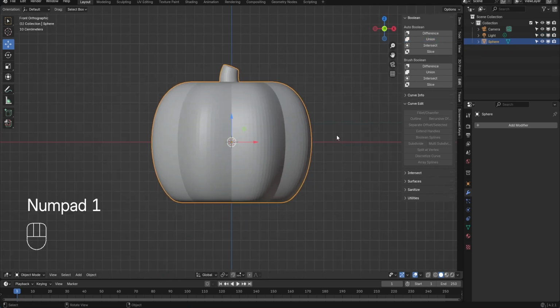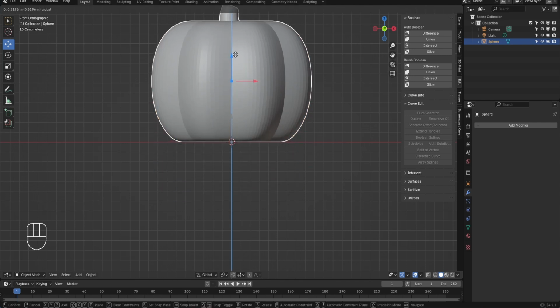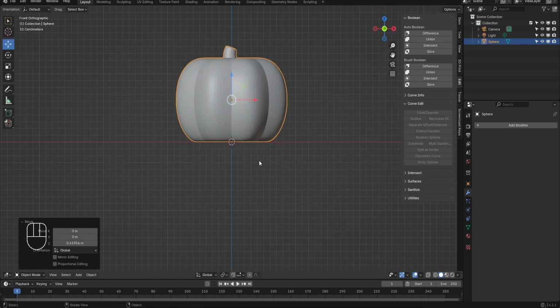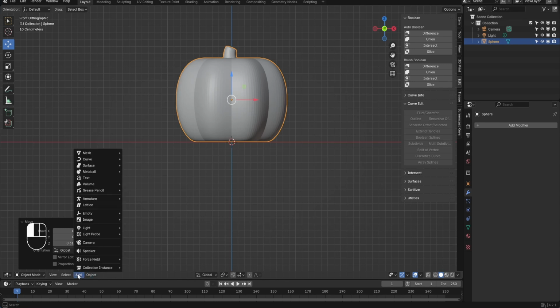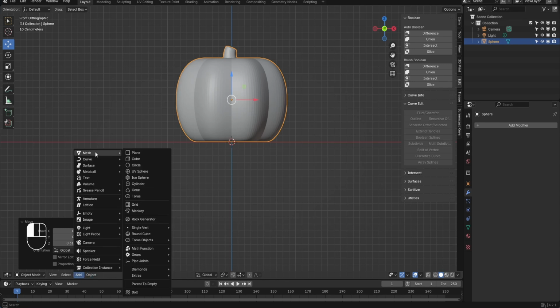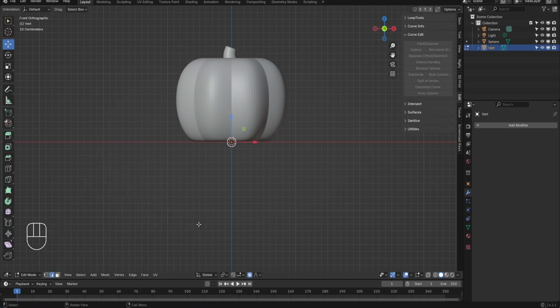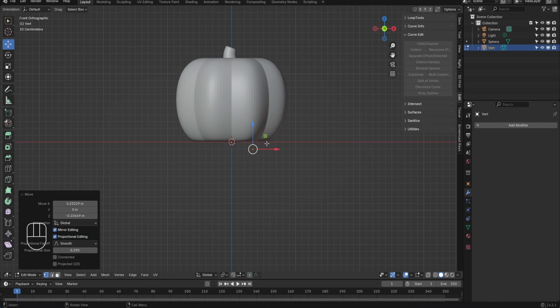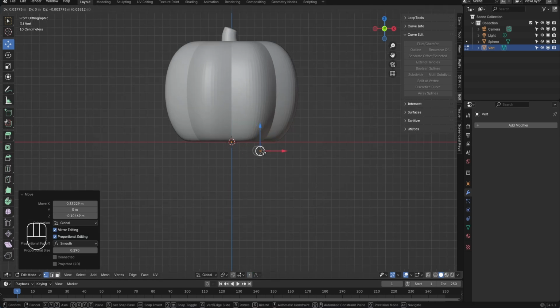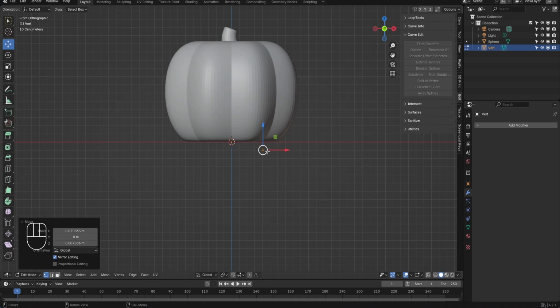Next, we are going to slice into the sphere, so let's move it up for ease of reference. Let's create the knife. In the Add under Mesh, select Single Vert, add Single Vert. In Edit mode, select Mode to Vertex Select and move the point so it's below the sphere and to the right of center. Here I forgot to deselect Proportional Editing, so deselect it.